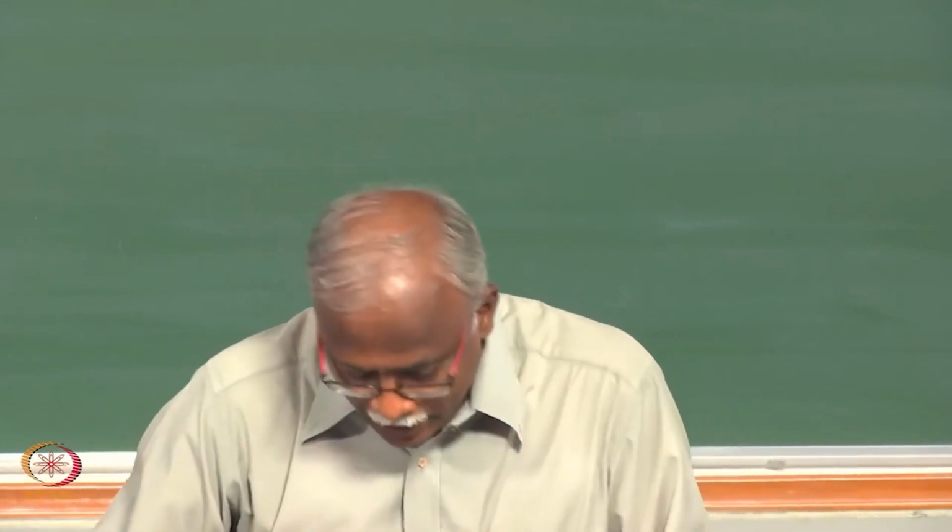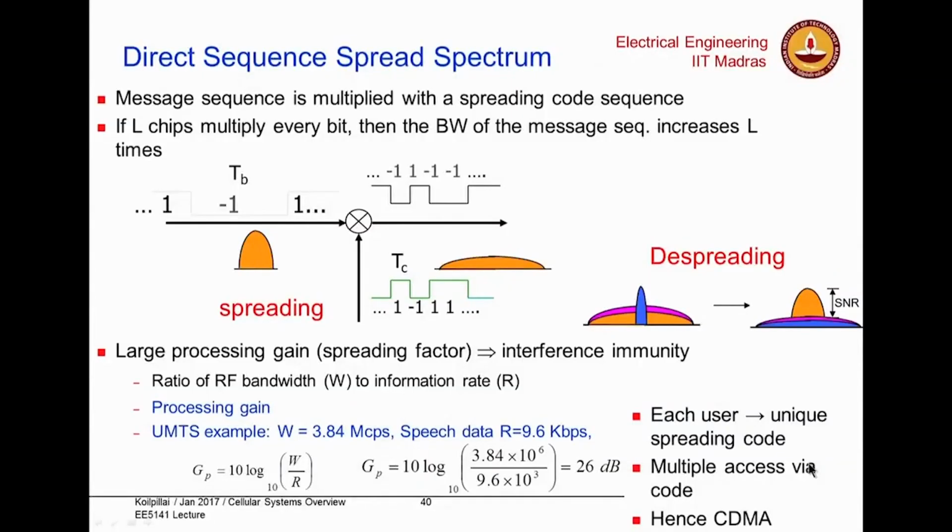a cellular system? And that is where, if you remember one of the early slides that we had discussed, the spread spectrum portion is the part where you take a narrowband signal and make it wideband, you spread it. Now, the key point is we have multiple users. It is not one signal that you are trying to hide. You actually have multiple users, multiple signals, and that is where you have the orange and the pink, and then eventually you have to recover these signals.